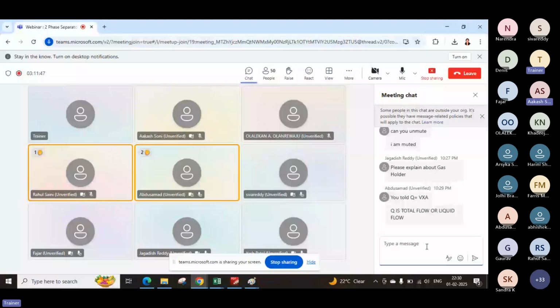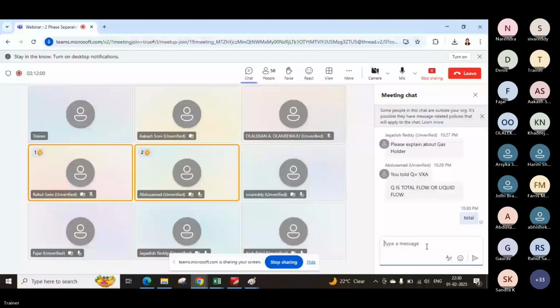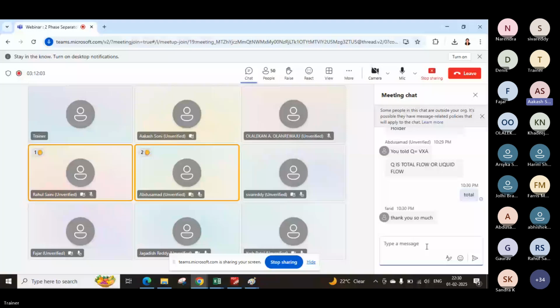Abdul Samad, at the start of your webinar you mentioned 10D, 20D. What is the meaning of 10D? 10 diameters, 20 diameters. 10 times the diameter of the inlet nozzle. Because diameter is also used for friction loss calculations, like a 90-degree elbow. No, no, that is L by D, that is different.